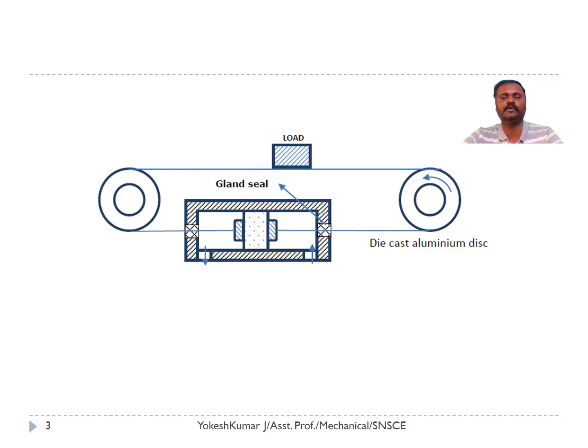So this is how the rodless cylinders can be actuated. For that we need a 4 by 2 or 4 by 3 direction control valve since we have two oil ports, to control the direction of the cylinder. This is the working of the rodless cylinder.